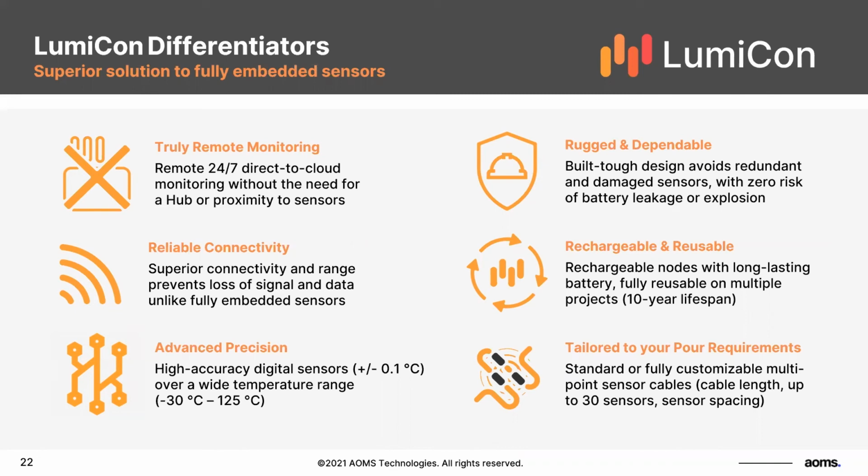Very advanced precision. Here we are not using thermocouples, we are not using thermistors. We believe in using a very advanced sensing technology here because concrete is important and maturity calculation is critical. So if you are dealing with a sensor product that has a low accuracy, like thermocouples or thermistors, you may end up with a high accumulated error for the calculation of the strength.